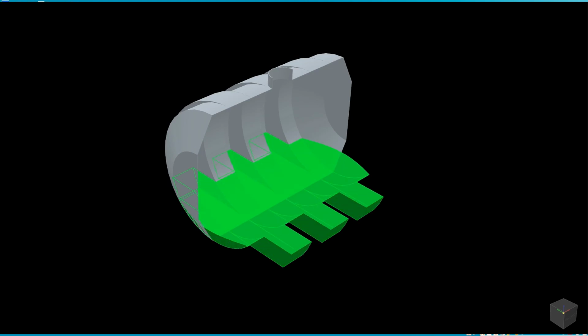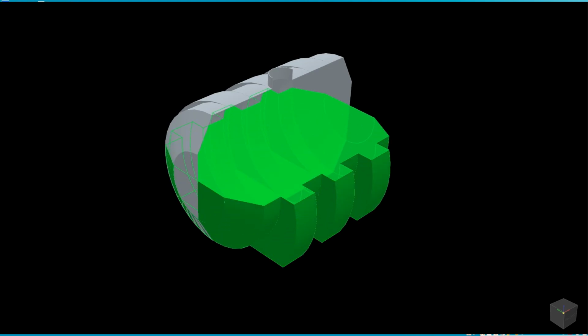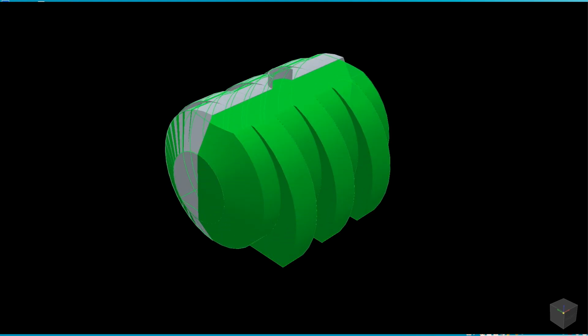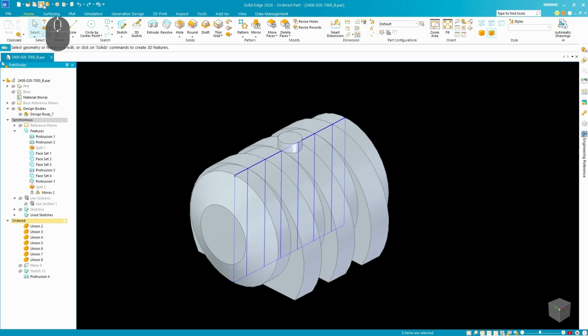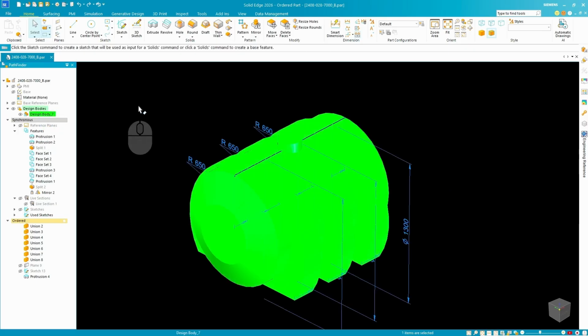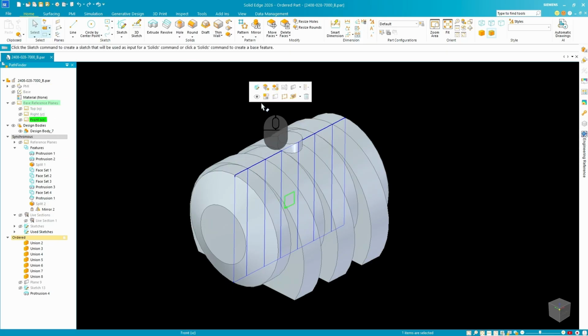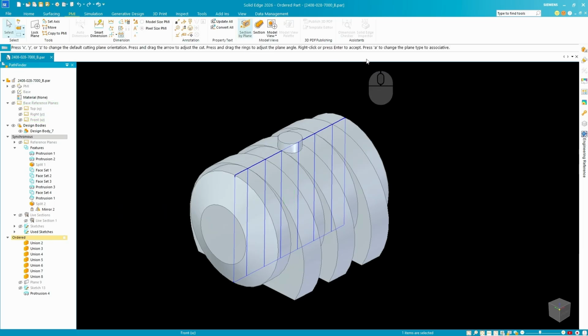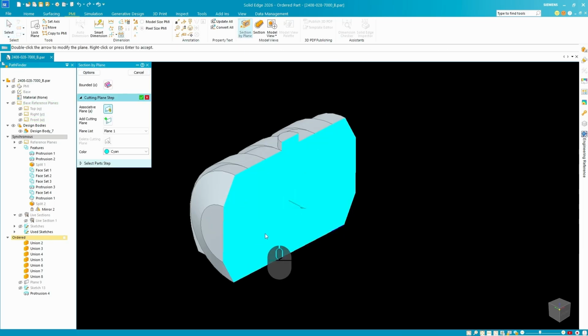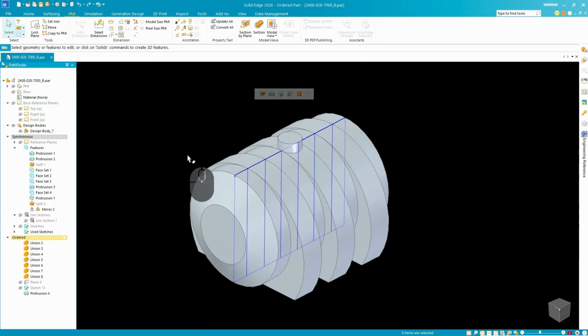Well, Joy, in this video we're going to use Solid Edge to figure out how much fluid is in a tank. So we have here a tank used for storing kerosene, and it's been solid modelled, and at the moment it's actually a complete solid block. It's not hollow. So if we choose the front plane, and go to PMI section by plane, you can see it's just one big solid block. And that's okay for now.